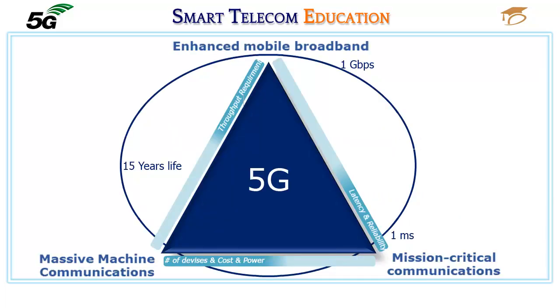The 5G wireless communications will be driven by three use cases of enhanced mobile broadband, massive machine-type communication, and ultra-reliable low-latency communication. The enhanced mobile broadband is designed for high-bandwidth internet access suitable for web browsing, video streaming, and virtual reality. The massive machine-type communication is responsible for establishing narrowband internet applications such as narrowband IoT. The ultra-reliable low-latency communication facilitates certain delay-sensitive applications such as factory automation, remote surgery, and autonomous driving.